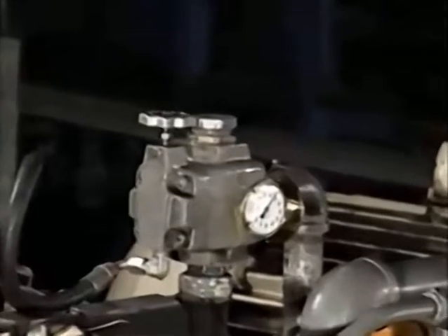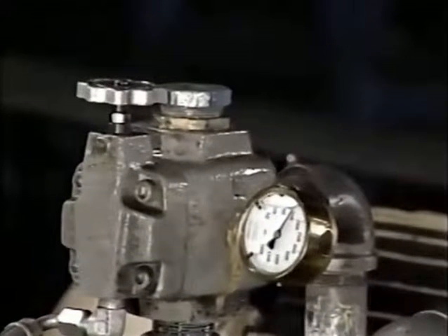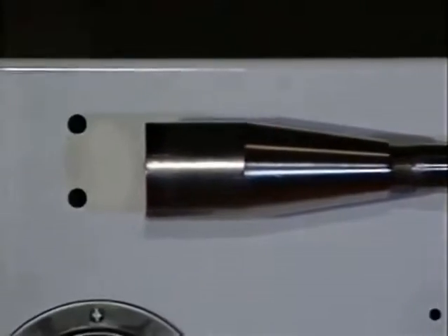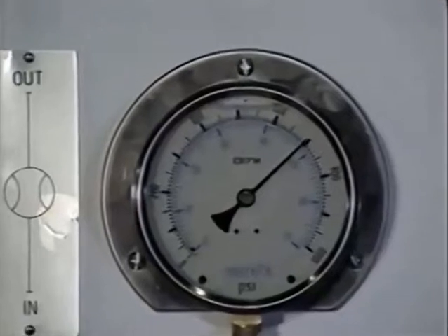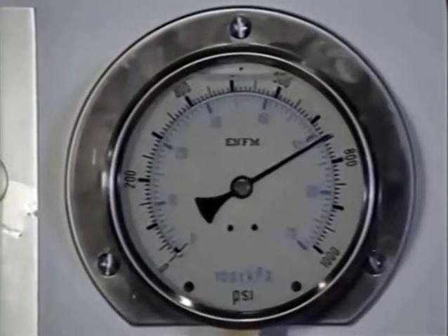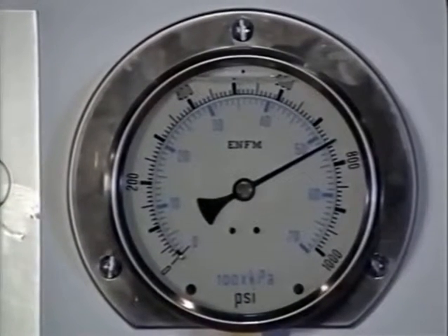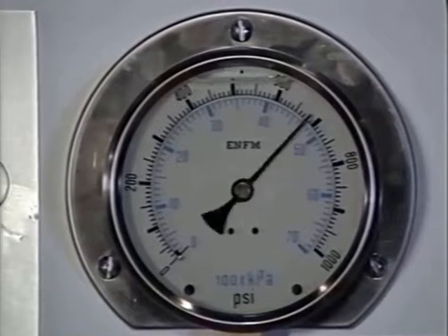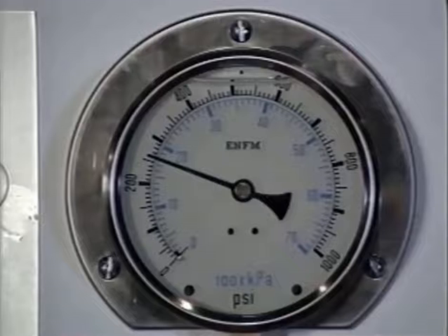Let's begin with pressure control valves. In a hydraulic system, pressure will increase to overcome the resistance of the system. For example, when a cylinder piston reaches the end of its stroke, pressure continues to increase. Without a pressure control valve in place, the pressure in the system could eventually rupture seals, stall the drive motor, or even burst piping. In short, pressures could reach unsafe levels.